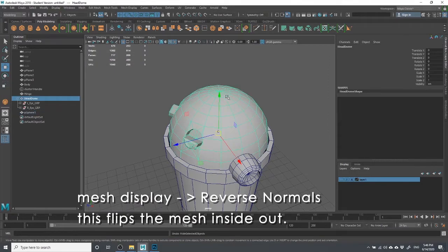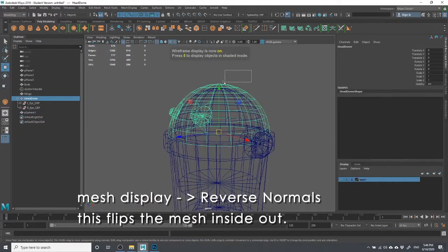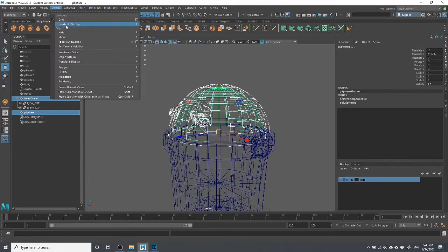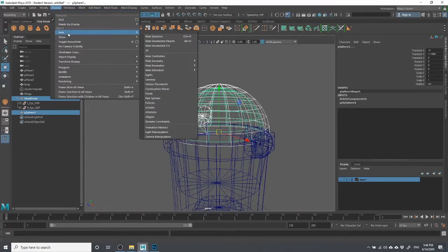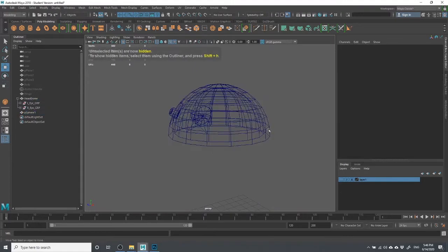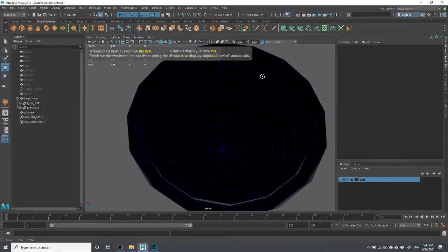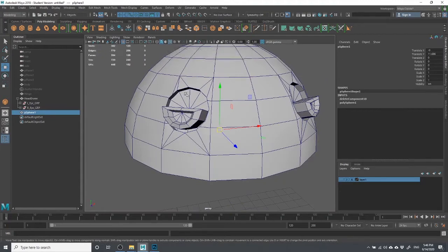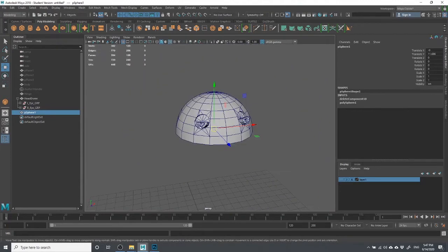I'm going to just temporarily hide everything but those two spheres. So I'm going to press Alt-H, and that is pretty much the same as going to display, hide unselected objects. And you get this here. The reason I did this here is just because the inside of this is simpler than these ugly sort of sockets in here. And I just don't want to deal with that here.